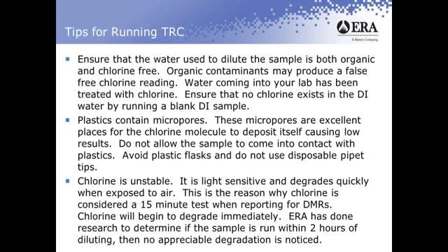ERA, my laboratory, has done some research to determine that if the sample is run within about 2 hours after diluting up, then you would expect to see no appreciable degradation. After that 2-hour period, you start seeing some degradation, and again, it might be only a few percent. But if you fail your DMR by 2 or 3%, I would hate for that to be because you didn't run your sample quick enough.